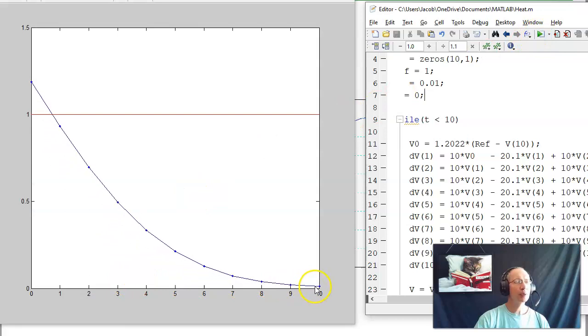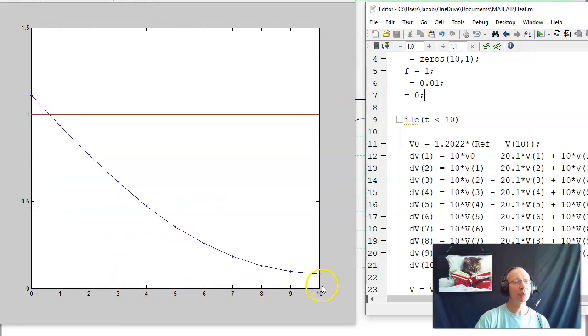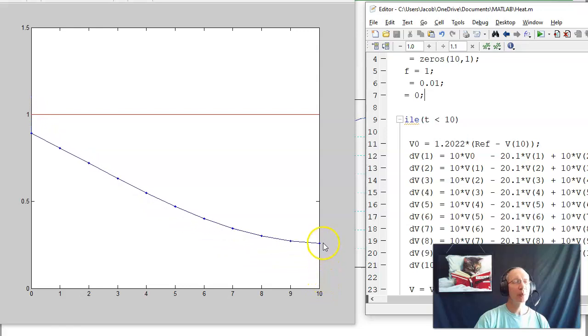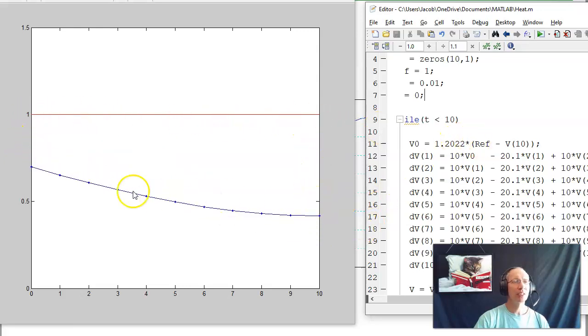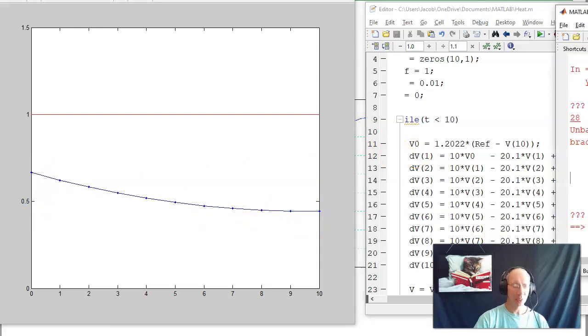Here's the step response. The step response in MATLAB showed node number 10, and notice node number 10 kind of paused, then it warms up. The input, the base temperature, is the difference between the set point, 1, and the tip temperature, times 1.202. If I make the gain 1.202, I get no overshoot. That's the quickest response I can get with no overshoot, and let's show that again.